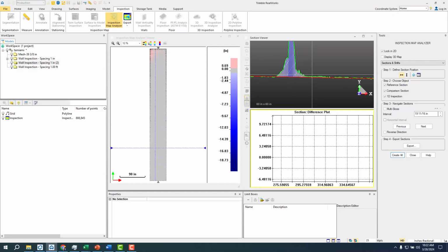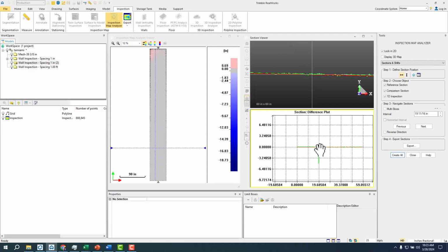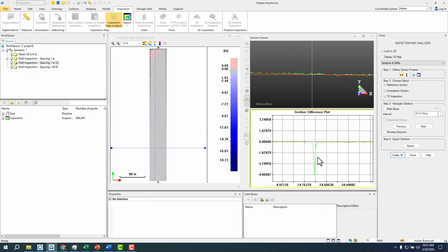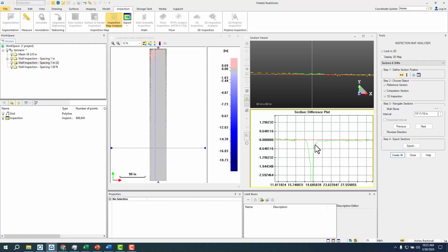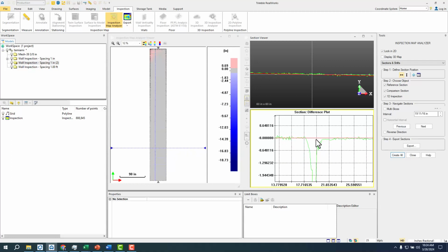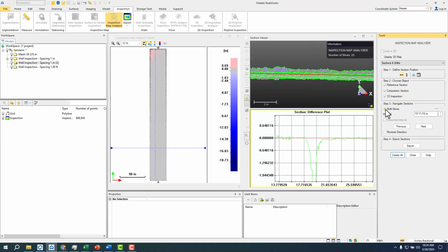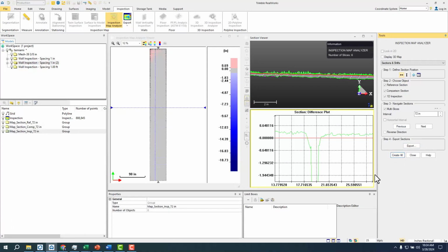And then I gotta find, and here I found essentially that scatter plot showing me this would be the joist, or the joint, and then I can start to see like the distance and gap there. But to do multiple slices, I'll do it every 6 feet. Make sure that's 6 feet. It'll actually run through, but if I create all these, I will have DWG lines actually showing me that.